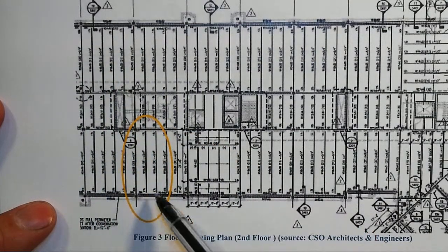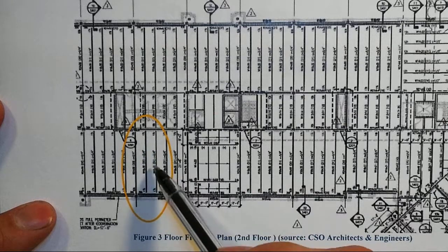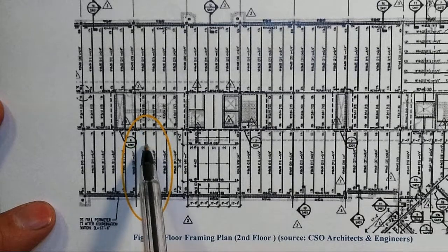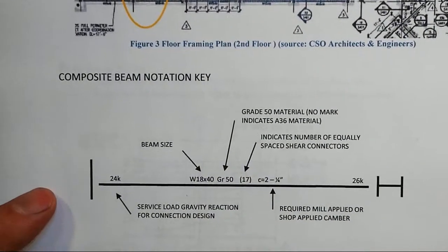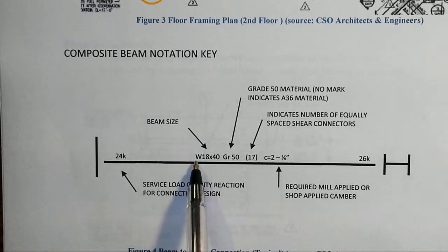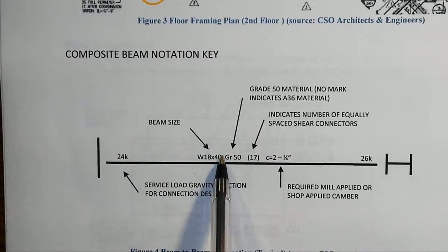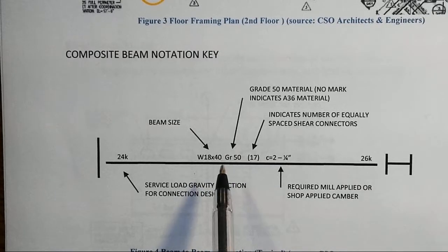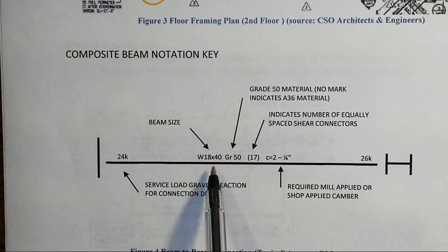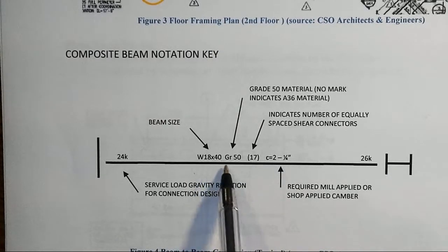Right? We're going to zoom in a little bit more on one of these little floor joists. In between the columns is a girder that supports other beams, and then this beam or joist supports the floor slab. And so notice what we get, kind of interesting information here for this particular designer. They tell us the size of the steel beam, W18 by 40. We talked about those cross sections before. That's about 18 inches high, 40 pounds per foot of self-weight of just the beam itself. And then it's grade 50 steel.